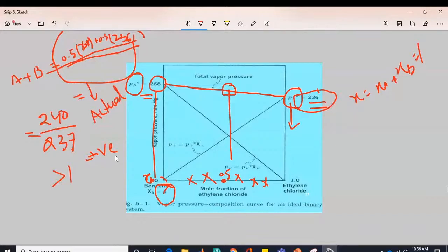Okay, let me go through the presentation again. Okay, now talk about molecular distillation. It is defined as the distillation process in which each molecule in the vapor phase travels mean free path and gets condensed individually without intermolecular collision, on application of vacuum, right? Molecular distillation is based on the principle of simple distillation with some modification. So this is the one major thing you need to know, that it is based on actually simple distillation.